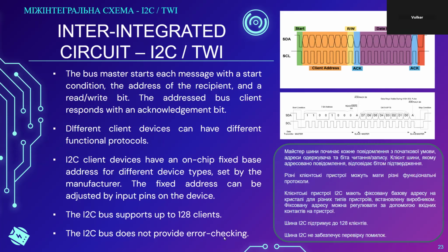With the I2C bus, the microcontroller will put the address of the intended device as the first byte, or 7 bits, on the data line, and clock that in, and the device that has this address will then respond with an acknowledged signal.